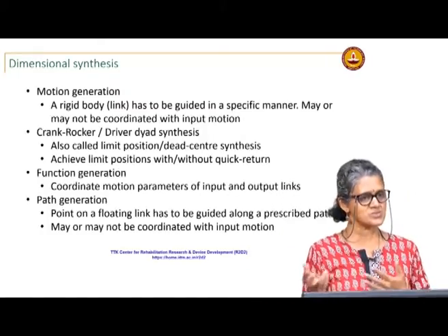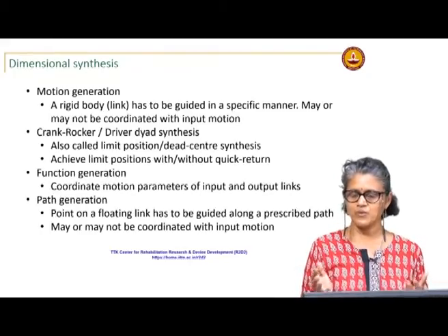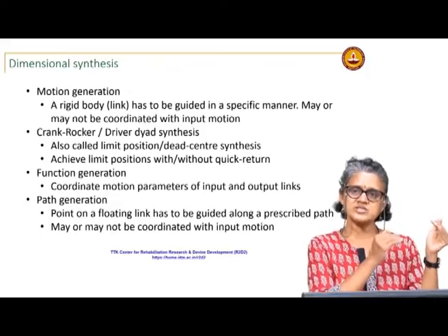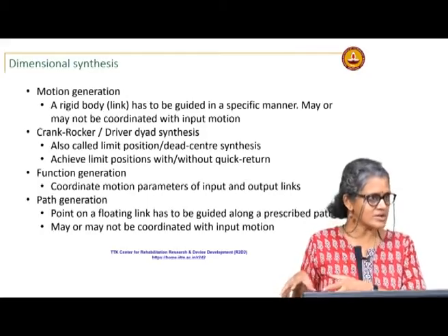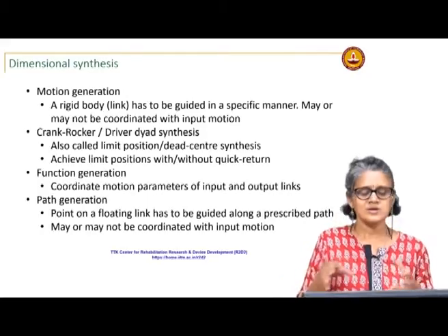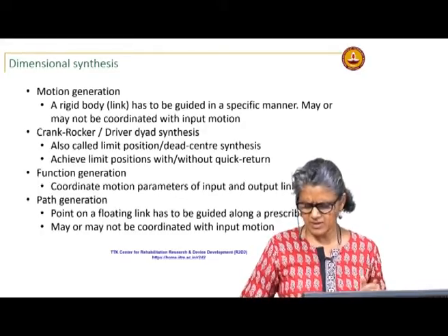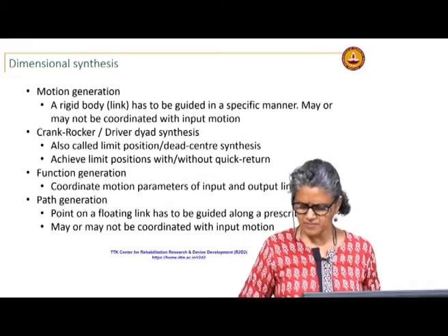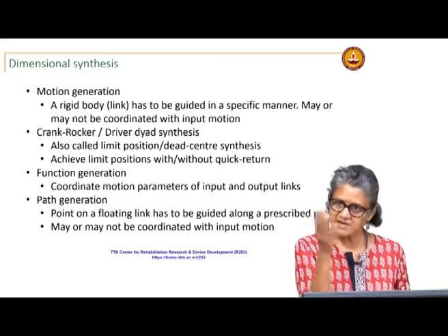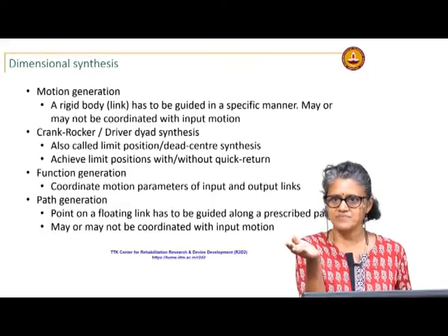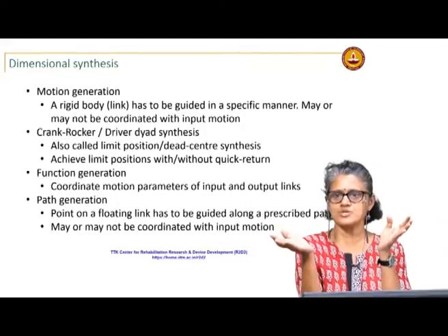In most cases we are designing a 4 bar and the 4 bar behaves the way it does. We are trying to narrow down which characteristic of the 4 bar we want for our particular problem. Any 4 bar, irrespective of what you design it for, will have dead centers and limit positions. There will be some relationship between the input and the output motion.